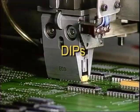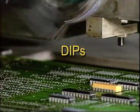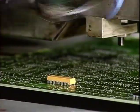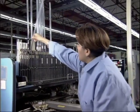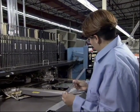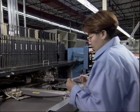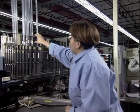DIPs are the most common through-hole IC. A DIP consists of 2 rows of leads, and the body is made of plastic or ceramic. DIPs usually come from the manufacturer in tubes. The tubes protect the components from ESD and lead damage and are designed to load the components into the feeders of automatic insertion machines for component placement.